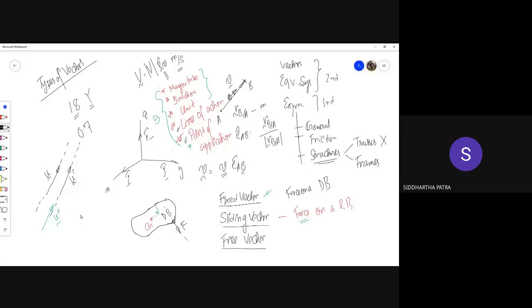The third one is a little complicated. So imagine you have a rigid body and you have a couple. That means a couple of forces which are the same in magnitude, opposite in direction, but non-collinear, acting on the same body, which means they do not give you an equilibrium. The net effect of the two forces is a couple moment, okay, a tendency of rotation.